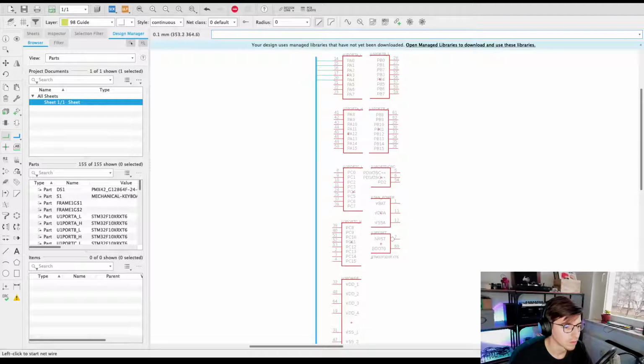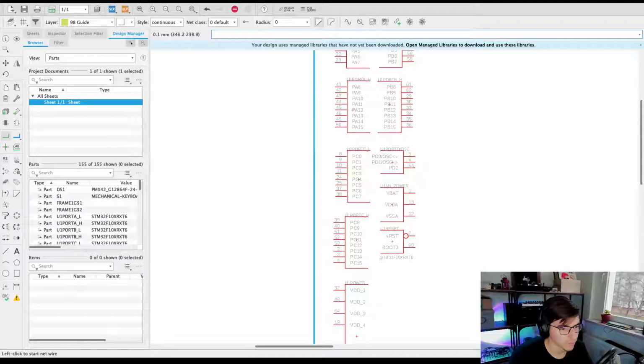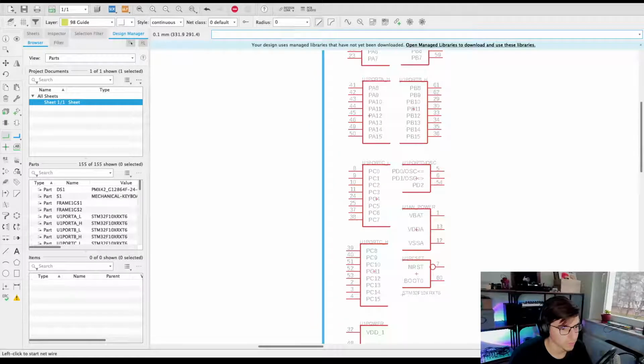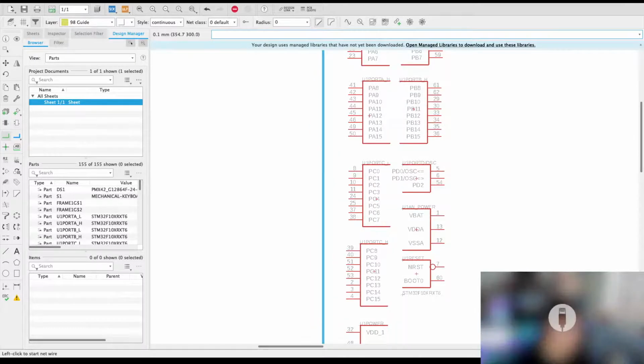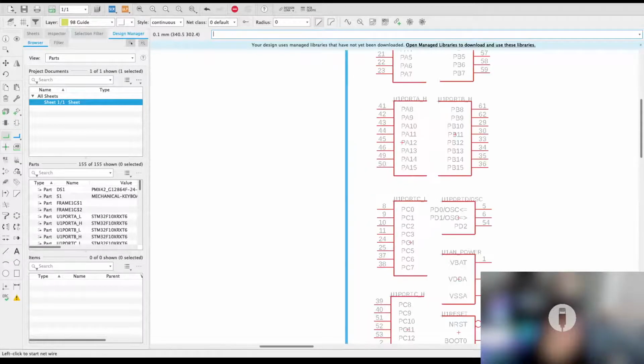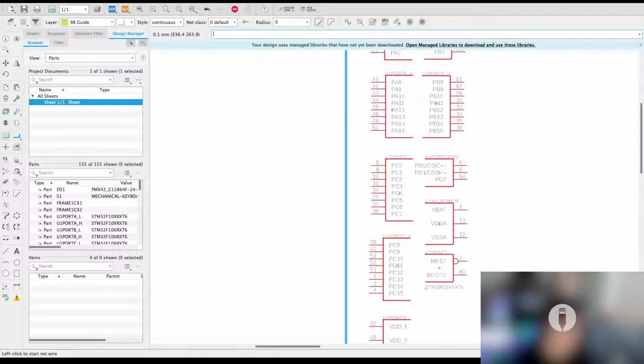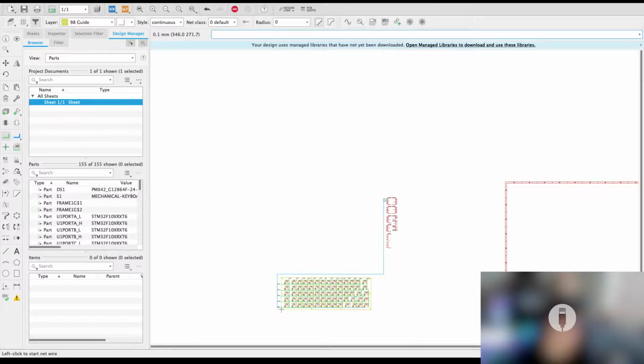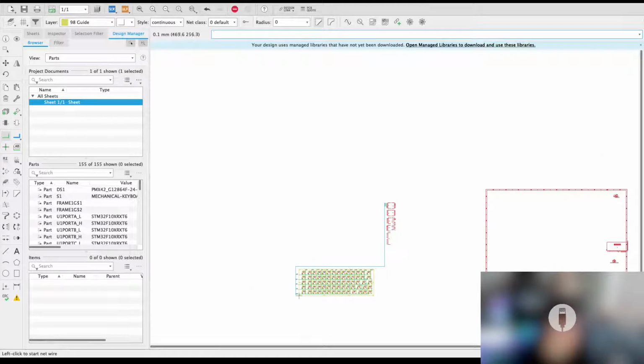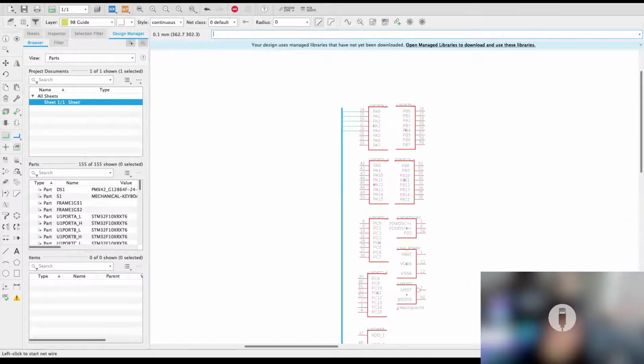So let's say the PA will be these ones, and it goes like that. So PA, B, C in this particular, and a couple of D ports, but it's not that important right now. If I remember correctly, any port can be a digital output anyway, unless some ports are necessary for talking to the screen or any specific thing.